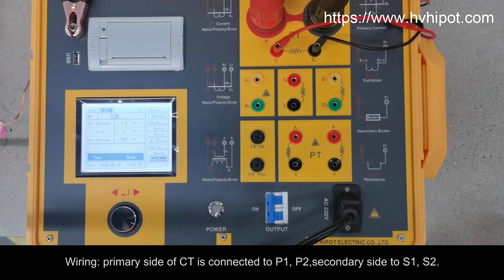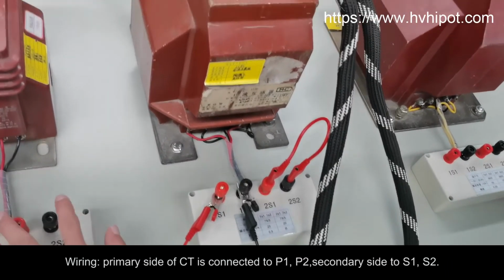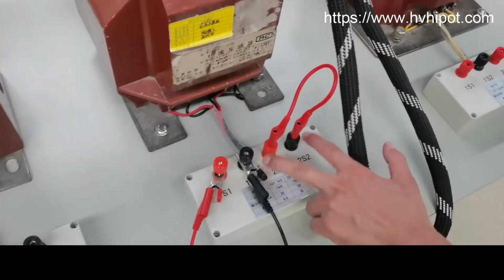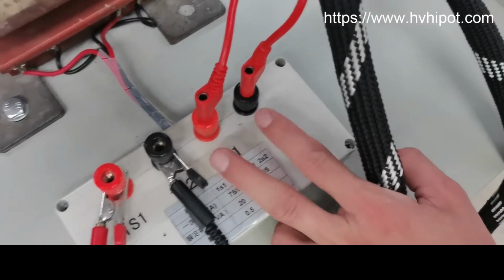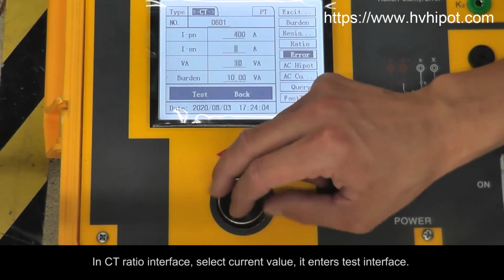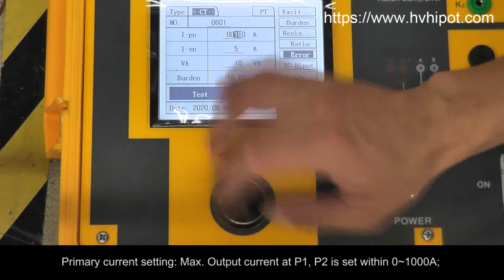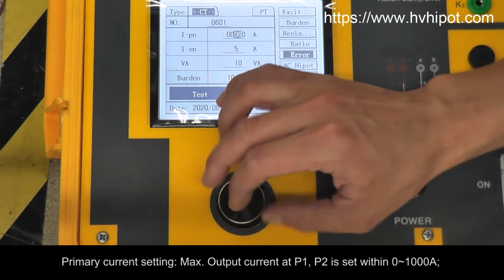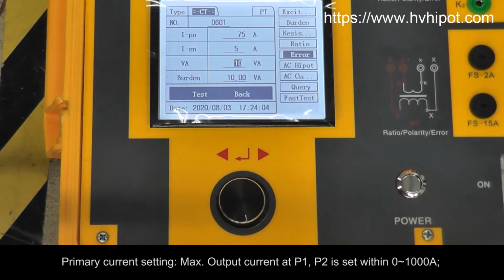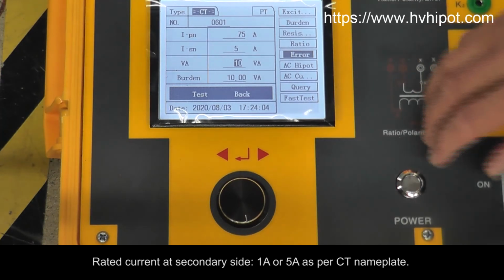Wiring. Primary side of CT is connected to P1, P2, secondary side to S1, S2. Short connect secondary winding that is not tested. In CT ratio interface, select current value, it enters test interface. Primary current setting, max. output current at P1, P2 is set within 0 to 1000 amperes. Rated current at secondary side, 1 ampere or 5 amperes, is per CT nameplate.